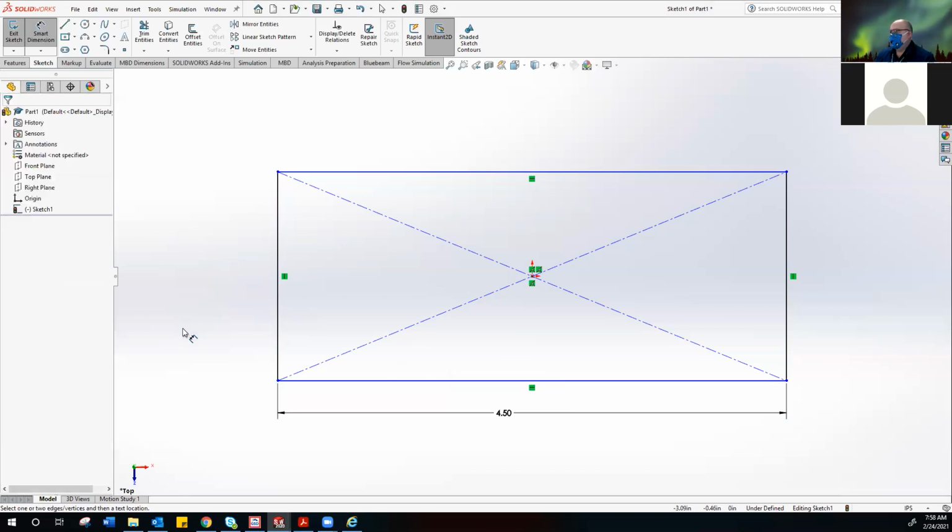That's a nice number. Now, since we did the center method, your vertical lines will be black, your horizontals will be blue, because we now know the distance from the center point. Because it's a center rectangle, it's defined by that distance. Okay, so we want to get to where every one of our lines is black.